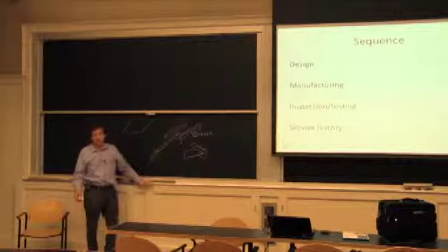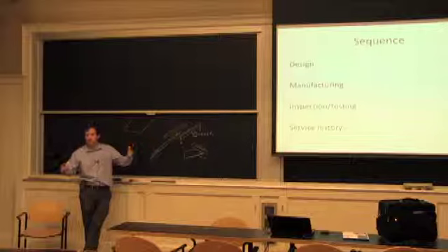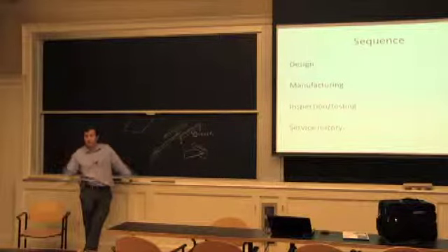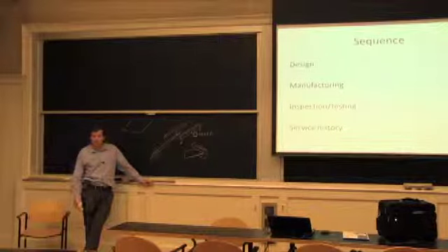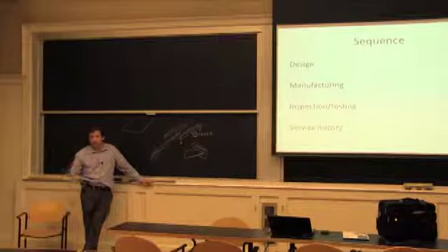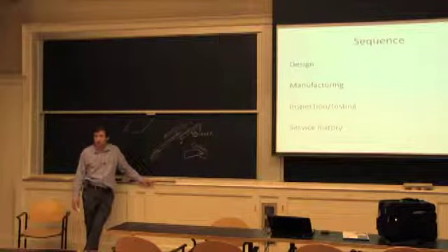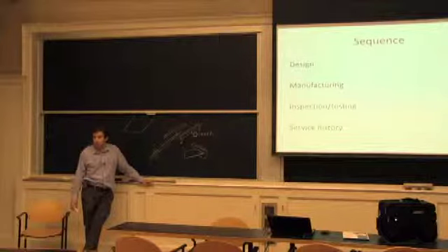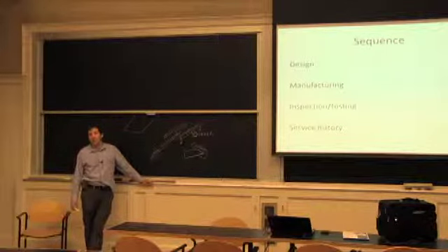It looks very obvious, but we've seen cases where people have ladders that on the drawing just say a 24-foot ladder, and then it turns out somebody put some welds in it because they only built it out of 16-foot long members. And there wasn't any requirement for the quality of those welds. They just made them the way they thought was going to be okay. And it came out to be a very big problem.